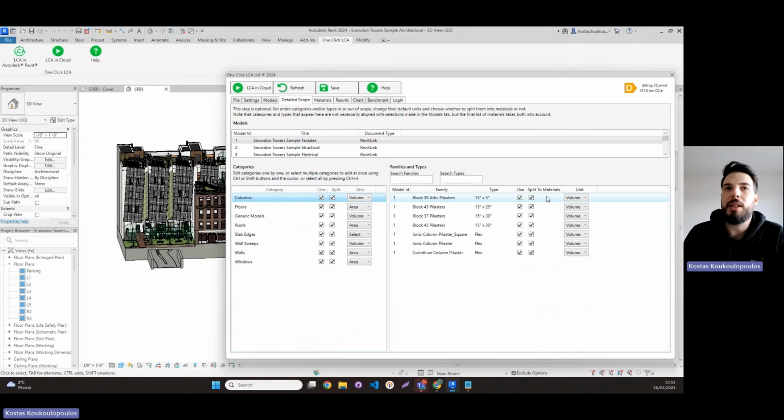So here there can be a common challenge that the Revit or the BIM models in general might be lacking detail. So the material layers might not be there, might be inaccurate, might be partially in place. And they might not be enough level of detail to do this correctly, or you don't trust them. So in that case, what we offer to you is an option to select if you wish to export the different objects as whole objects or breaking them down to materials. Breaking the object down to materials, of course, can be more accurate because you get all the layers.